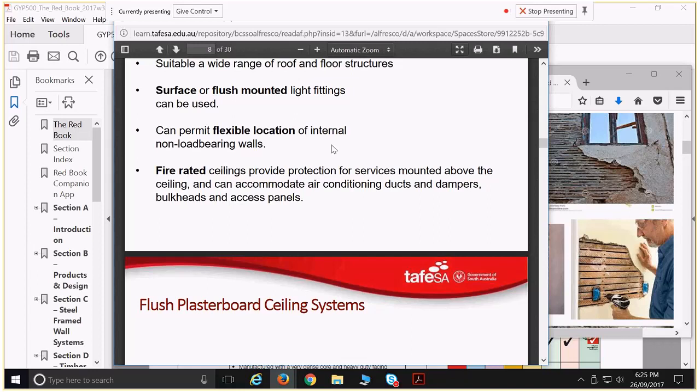The builder will always put the ceiling joists in at 600 apart, all of them, and then this last one at a gap of, in that case, 400 millimeters. The reason for that is that the sheets of plasterboard come in 600 millimeter increments. So what we don't want to do is say, all right, space joists at 500 millimeters, for example. We could write that down on the drawings and dimension the whole thing up. It's not going to happen like that.